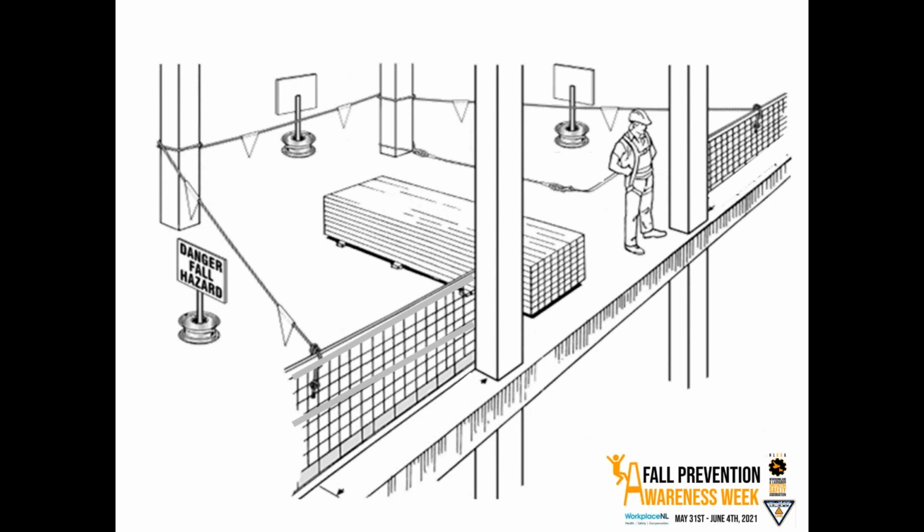Again, signage is really important on construction sites, especially because it's a changing environment. You might have people who are popping into the work site on a particular day. They haven't been there in weeks, and they didn't know that this type of work had begun. And they weren't sure what to do when they got to, say, some flagging. Maybe they needed to access something in the unsafe area. So you want, again, some kind of soft barrier, ideally set 6.5 feet back from that edge, or a hard barrier, certainly, if you don't have that much room. And again, you want your signage present.